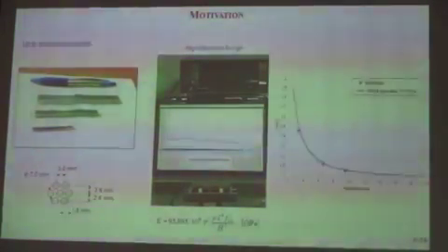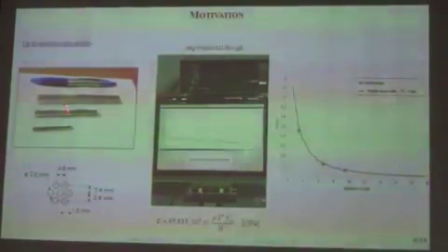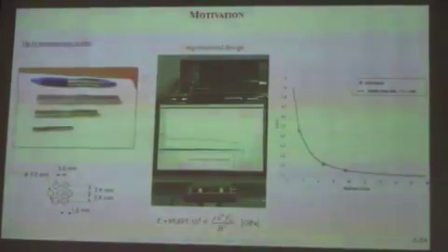When I did this, I immediately got a bending rigidity that increases if the sample size decreases. If I use the coupled stress approach, which is commonly the easiest one at this stage, I will explain it a little later, it gives a fitted material length scale parameter of 1.5 millimeters, so something in the range of the microscale.